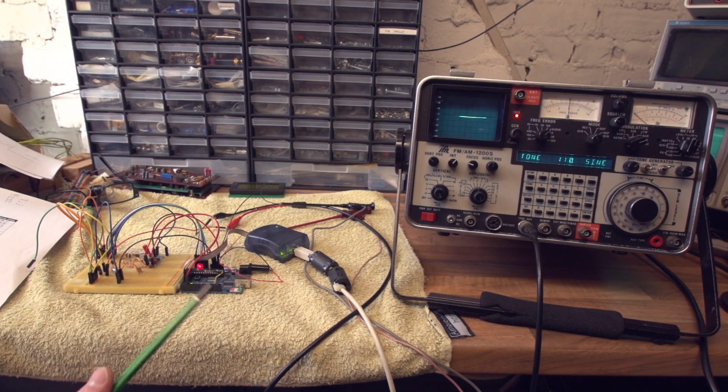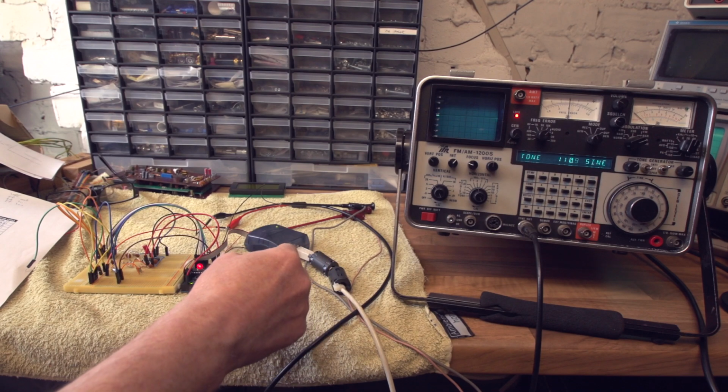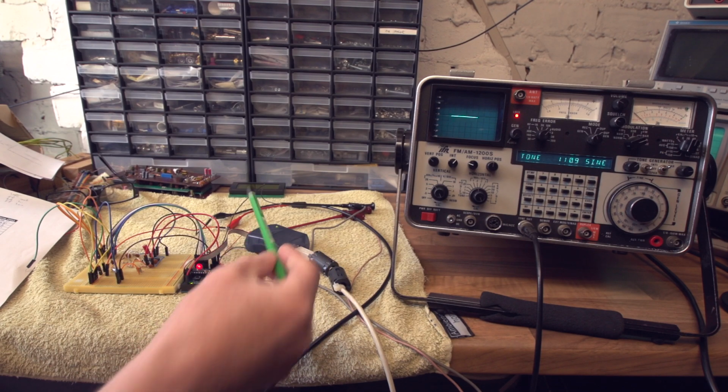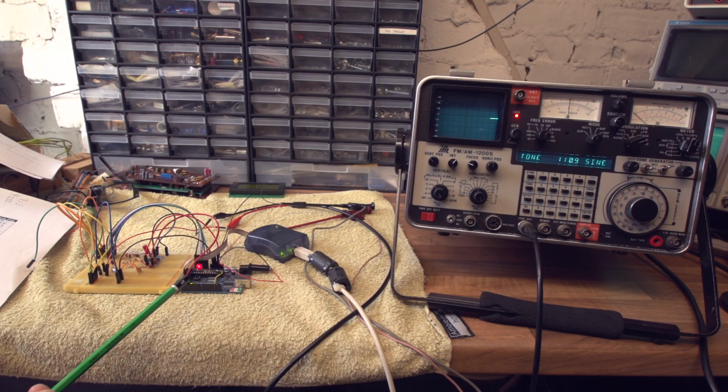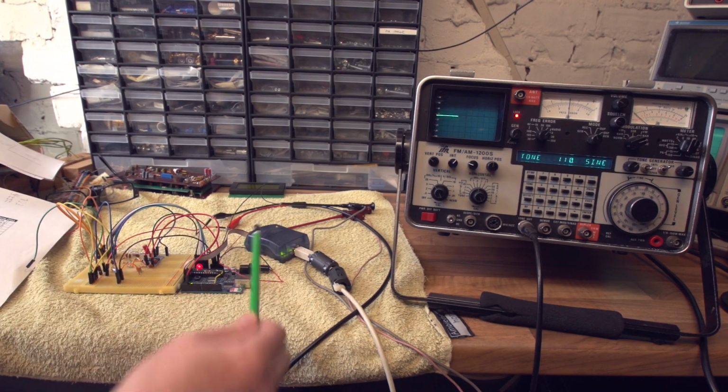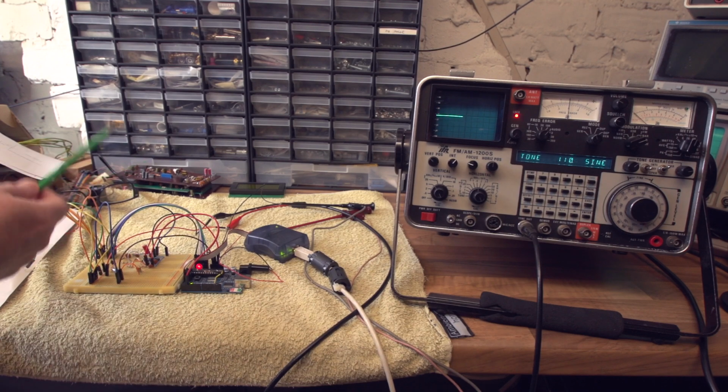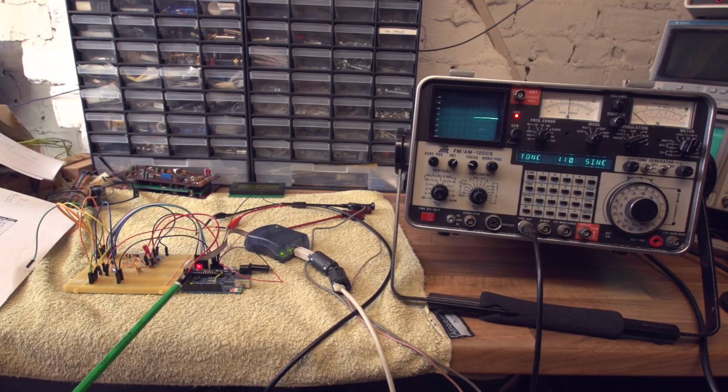The output from the software from the Arduino is driving this single red LED, giving us a signal of whether the CTCSS tone is present or not present. So we've modified the software, display is gone, and we end up with a single LED. That's our logic state, which will go to the controller card.